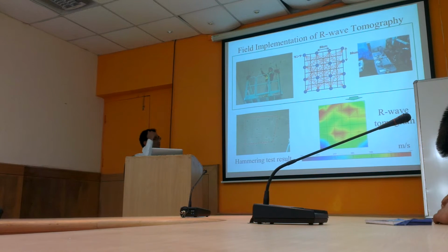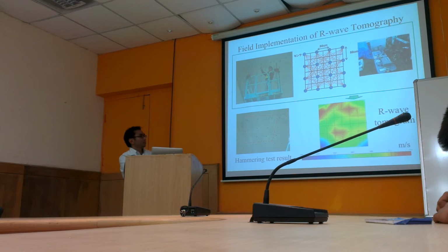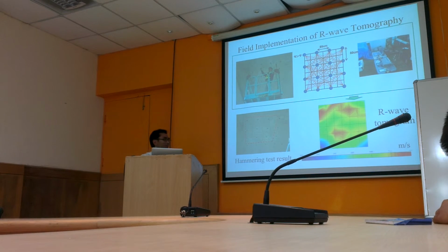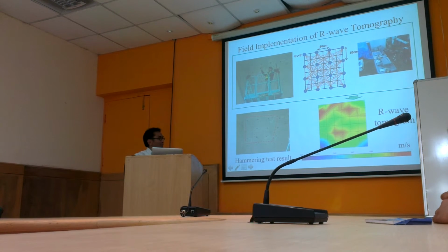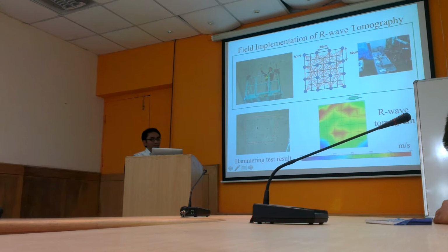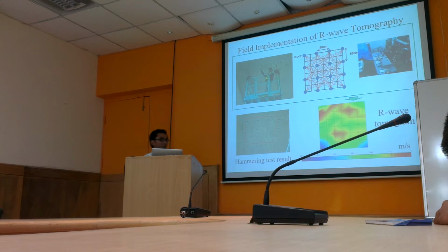Another example is that we try to utilize this for actual measurement. We went to a bullet train bridge deck in Japan, and we did the same thing. And this is the result. Actually, these are the results based on the impact test. You just knock it and listen to the sound. So the markings are based on the change of the sound. Now, it might not be very accurate. And this research is still undergoing, and we still have a lot of unsolved issues. We are trying to find a balance so we can continue this research.